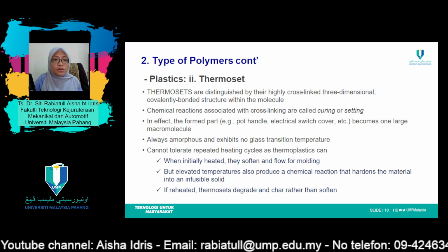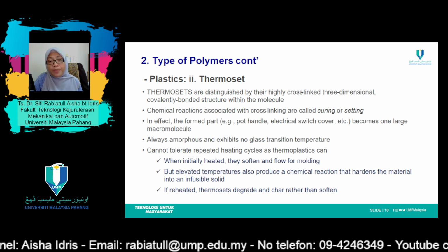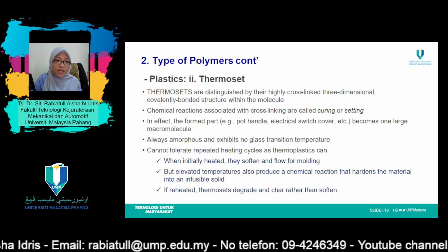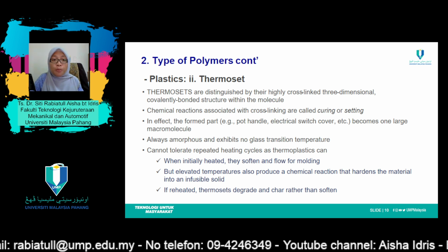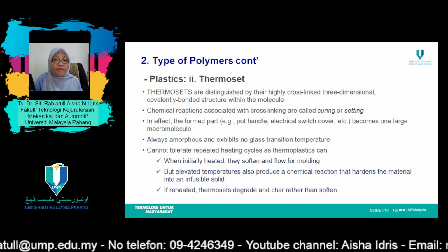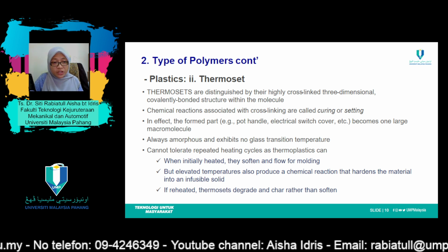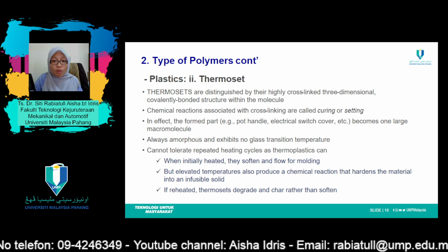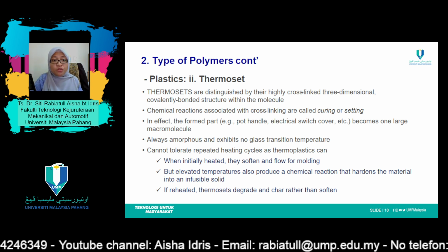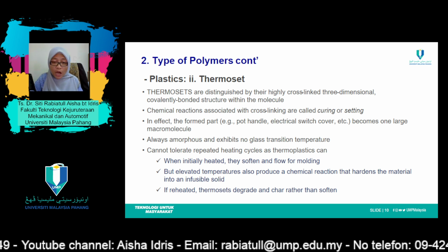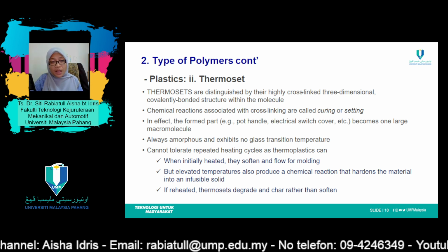Whereas thermosetting polymers are network polymers. They become permanently hard during their formation and do not soften upon heating. Network polymers have covalent cross-links between adjacent molecular chains. During heat treatment, these bonds anchor the chains together to resist the vibrational and rotational motions at high temperature, and thus the materials do not soften when heated.